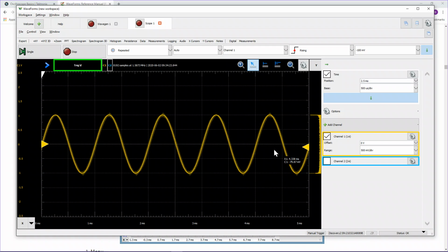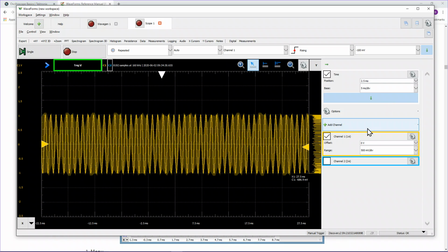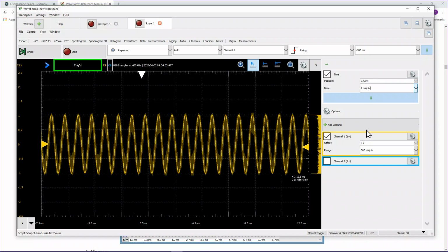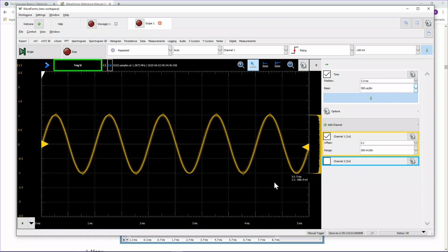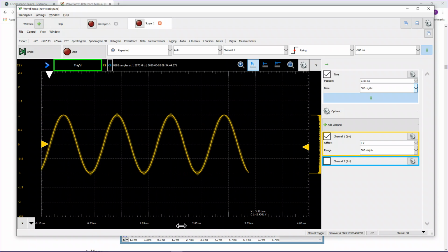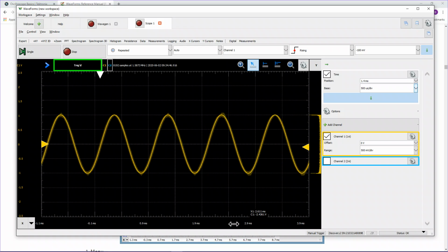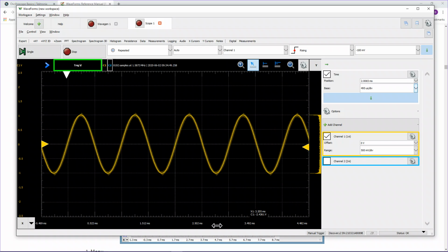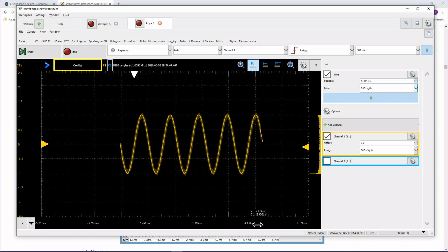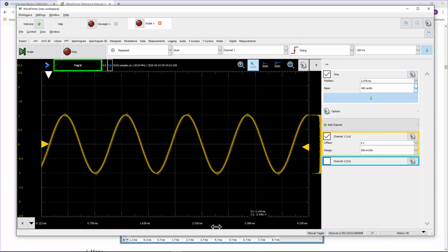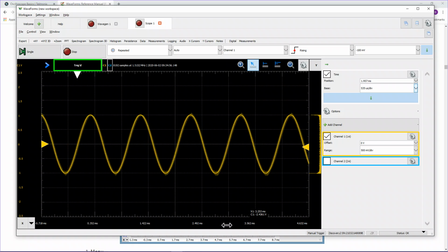So that gets us to being able to adjust what they would call the time base by changing this value, and with our waveform applied to the input, it looks like we might be changing our waveform, but we're really not. Also, you can change the display by dragging down here with the left mouse, but you can change the time base by holding the right mouse in and doing it. That's an advantage of having a computer user interface.